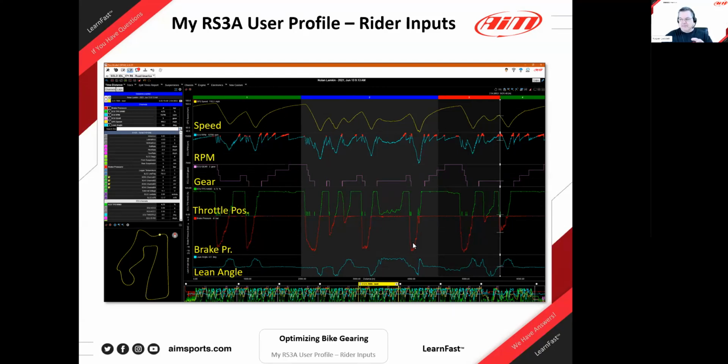One of the things I'd like to jump in and point out is that you do something a little bit different here than a lot of people do, and it's intriguing, and I think a lot of people may want to use it. It's compiling the throttle position and the brake pressure one on top of each other, flipping the brake pressure, and showing it as a continuous line coming down from the throttle. If the rider comes off the throttle and gets right after the brake, this is going to be basically a straight line right into the braking pressure, and then the same thing coming back up.